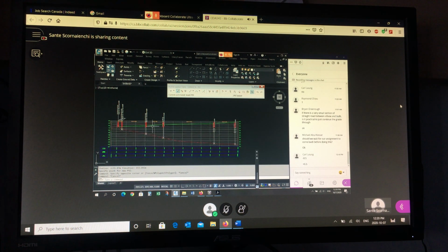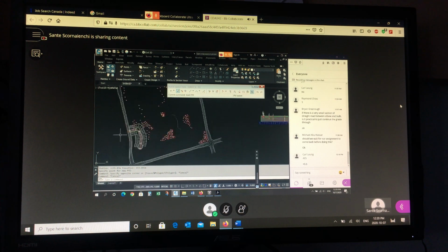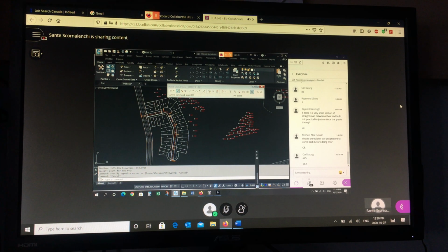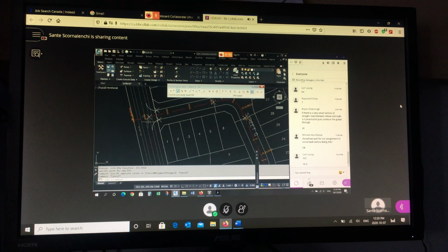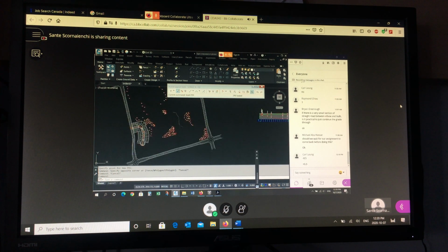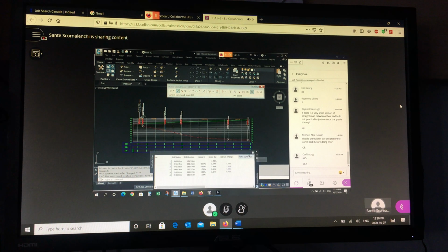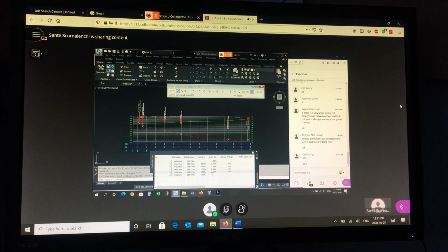The station values in the design profile are actually key locations in the plan, where your elbows, where your cul-de-sacs, and where your intersection low points are. So the points in the plan dictate the location of your profile points, station values. The elevations now are taken care of. If I go back to that grid, if I change the slope, it's actually updating the elevation. The elevations are changing when I change the slope. So if I change this to 2%, the last number is going to go up. So it's adjusting the slope as we go.